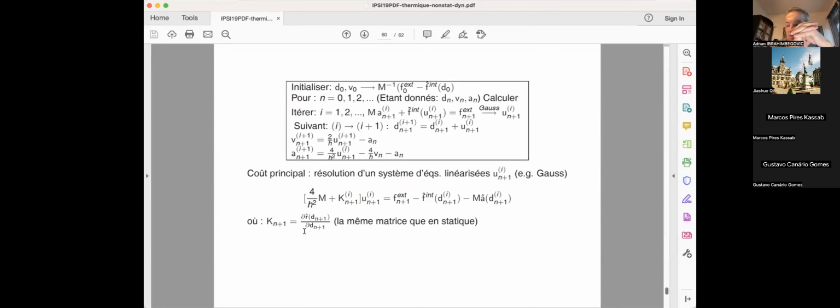Typically, if you really have problems obtaining the solution, many people artificially add dynamics because dynamics make things more regular, more smooth, and then you can compute these things in a better way. I talked to many colleagues who did research before me, when they didn't have this powerful computing. They studied instability of shells by pretending to go into dynamics.